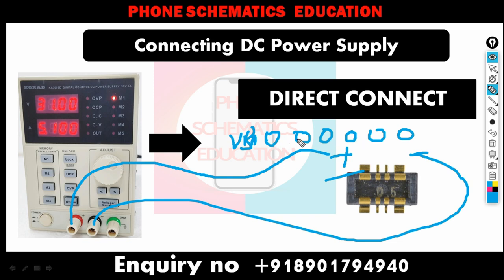Whatever pin beeps, like this one, this is VBAT. So you can take a jumper from here and connect it to the positive line from the outside, and connect the ground, the black probe, to any shield on the motherboard. After that, press the on/off button, find the short circuit, I mean diagnose the phone. So this is one way.